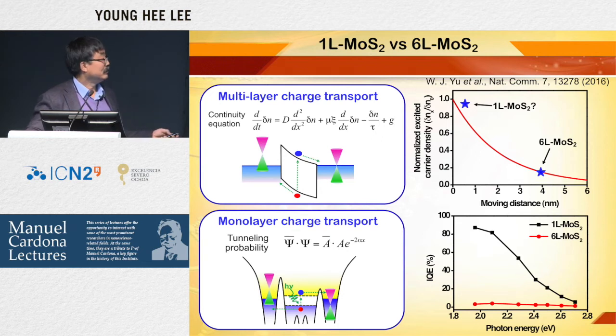van der Waals charge, and we do have strong electrostatic potential. Because of this different environment of graphene, here the Fermi level on both sides is different. So we have an asymmetric electrostatic Coulomb potential. And when you excite carriers in MoS2, this one can easily transmit, but cannot transmit this way. This is how it contributes to the photocurrent. Of course, if you increase the energy much larger, then there is no difference between these two. Then you have the same, and the photocurrent is reduced. This is actually what we observed in the device.